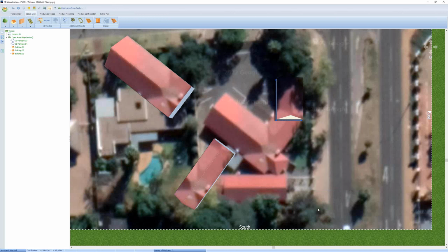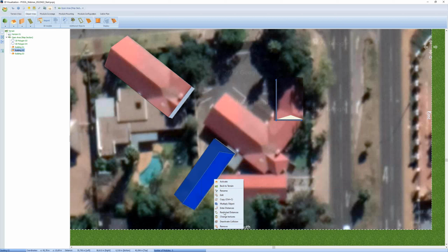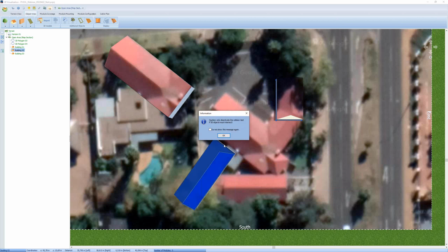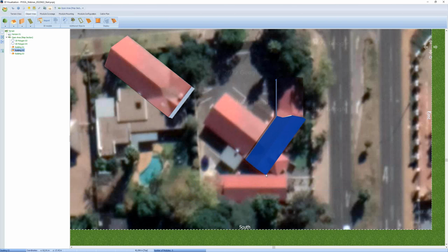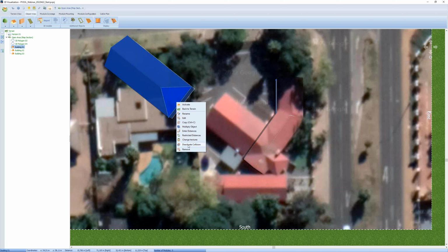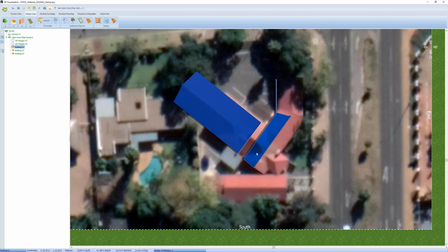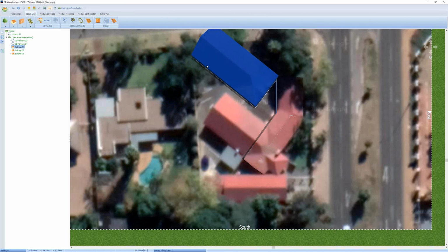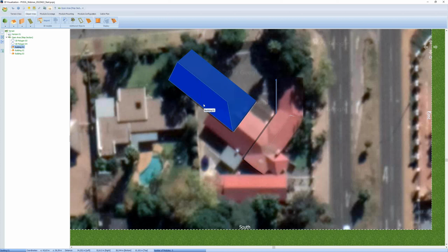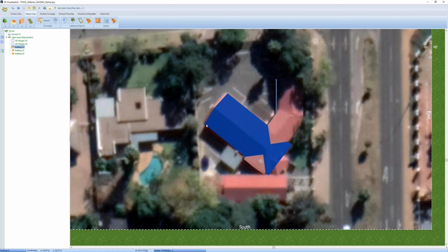Okay, now we have to bring all buildings together to our example here. Means we have to deactivate the collision. Okay, and then we can shift it into each other here. And we have to do the same. Maybe you can show, if we don't deactivate the collision, then you can move it into each other. In this case, yes. I'm surprised, this one is deactivated. But in the upper part, it's not possible, as you can see here. It's not possible to move it into each other. But because here we have deactivated, it would also be possible for this building here.